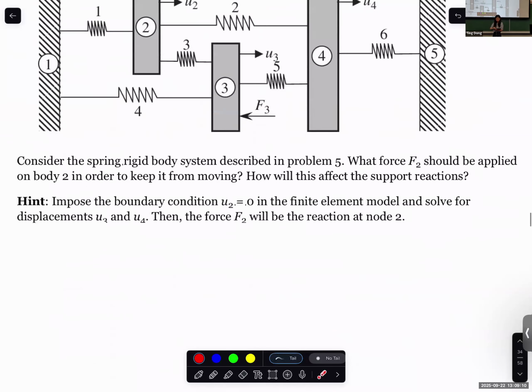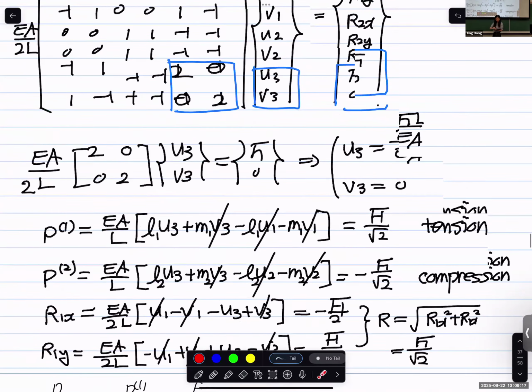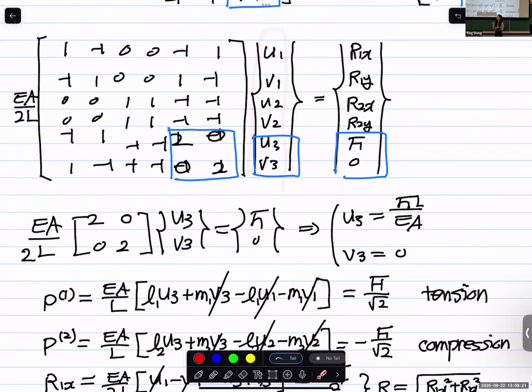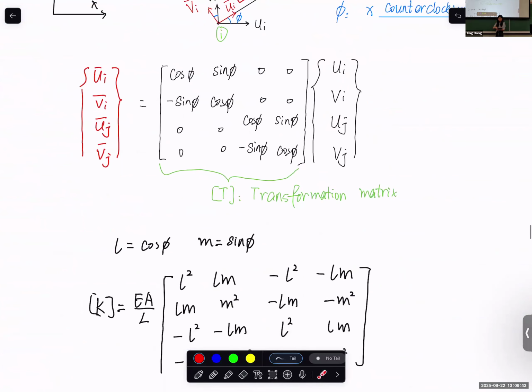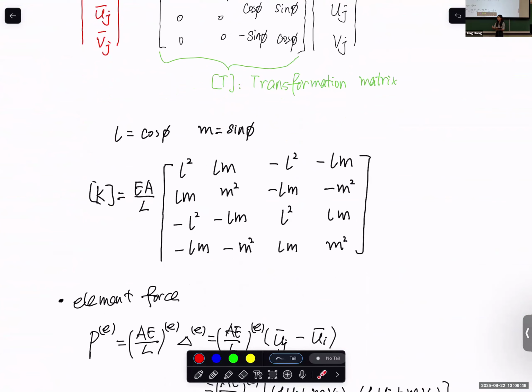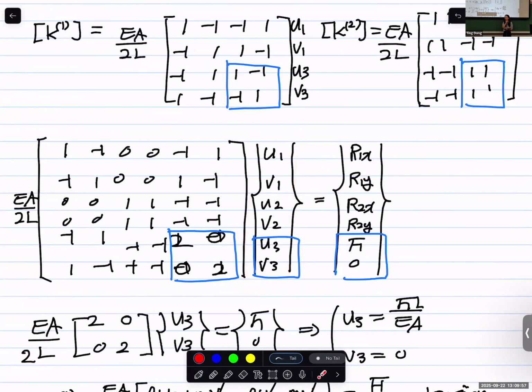And also in the global 2D space, when we set the equation and everything, it is always in the global xy coordinates. We always have this one as positive x and upward as positive y. So whatever you solve is only in the global xy coordinates. It does not depend on whether I define 1 to 3 or 3 to 1, which is the local x direction. In the end, we convert in the theory part. I didn't put a complete derivation of the theory here, but if you check the detailed derivation, converting from 1D to 2D, you will see that in the end it is solving the displacement degrees of freedom in the global xy coordinates. And as long as we have the global coordinates, it doesn't really matter, right?